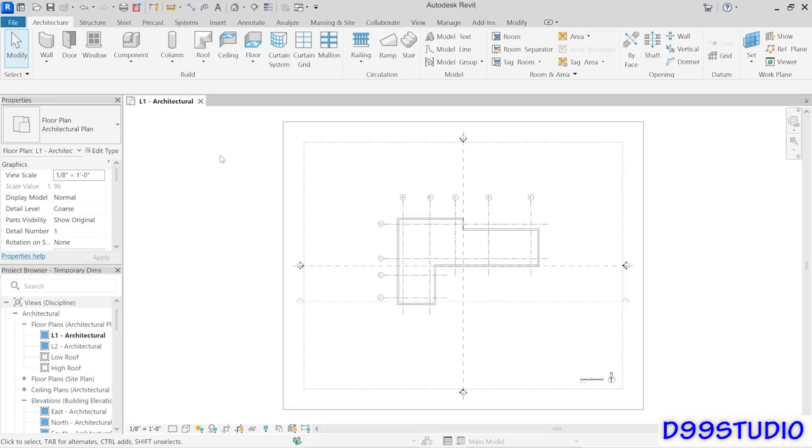I want to demonstrate that process here, and I'm going to use a really simple example. I'm going to focus on these column grids that we have here. If you watched the previous video where we placed those column grids, it might have surprised you that I was just placing them randomly without really thinking too much about where they were. I didn't use any dimensions at all, any numbers at all. Well, that was intentional because, again, I was just roughing out my idea that I needed grids in these approximate locations. Now what I'm going to do is come back and refine those positions. I'm going to take that sketch and modify it. I'm going to progressively refine that layout. We're going to do that with a feature called temporary dimensions.